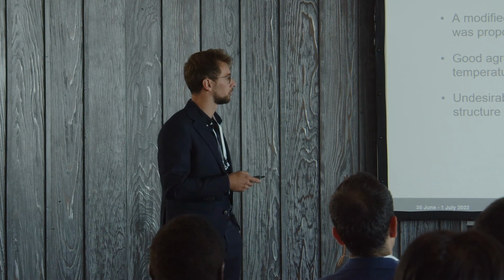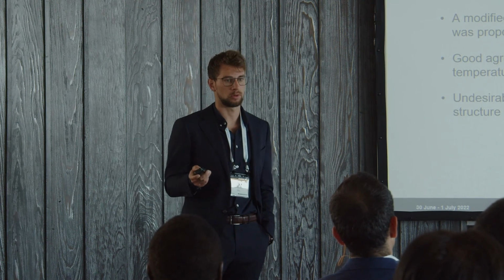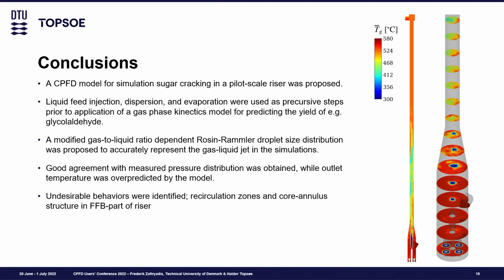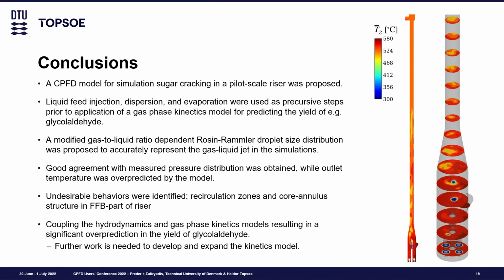And then we're actually able to use the CFD model without the kinetics model just to predict some of the recirculation zones and undesirable behaviors in the fast fluidized bed part of the riser. And then the big problem, definitely, is the homogeneous gas phase kinetics model that we will be working on expanding.